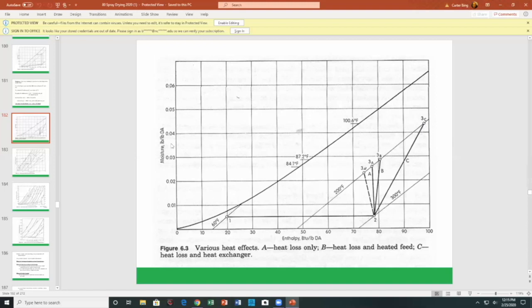in this region. So I'm going from about 28% moisture, 0.28 moisture, say in this region, up to 0.043 moisture in this region. So I have a substantial increase in moisture being picked up. And again, this is an exchanger inside the drying chamber, right?